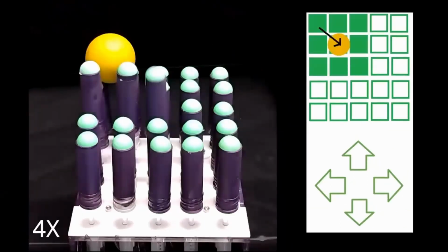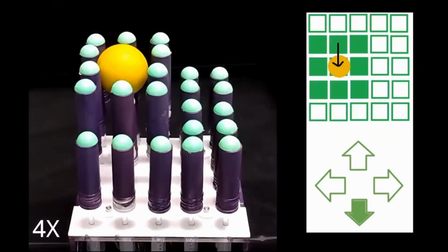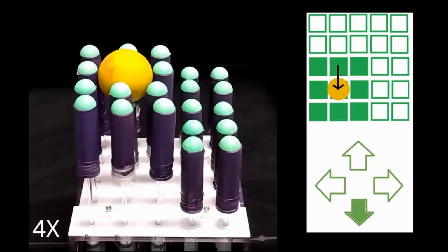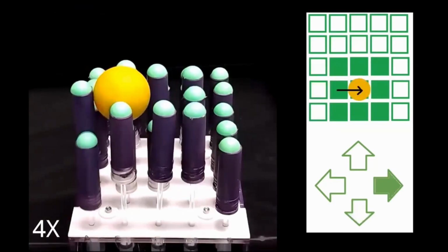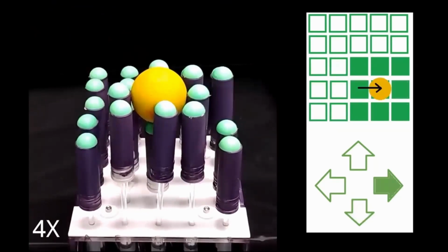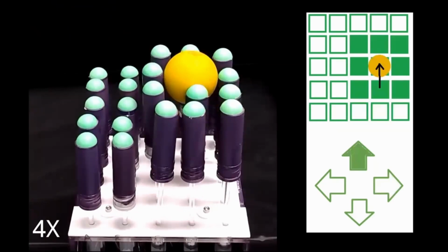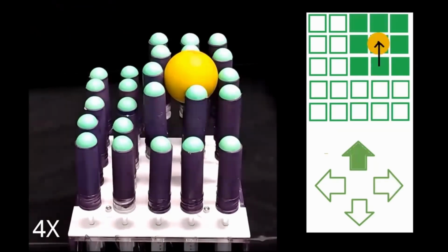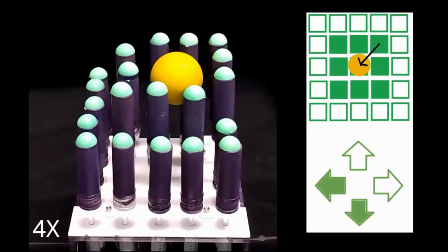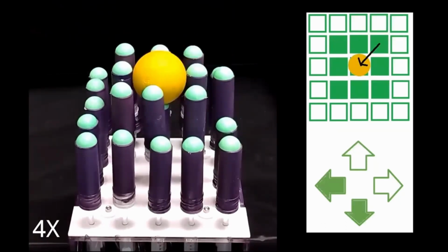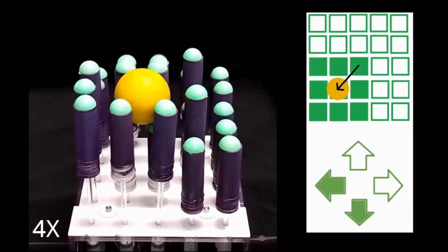We also demonstrate the use of a 5x5 shape display controlled by a fluidic matrix circuit to generate desired patterns to convey and manipulate objects. The tactors were used to generate height profiles to confine the object within a cage and to guide the motion of the object along the desired path. We demonstrate the pattern generation for object manipulation to convey the ball along a row, a column, and a diagonal of the shape display.